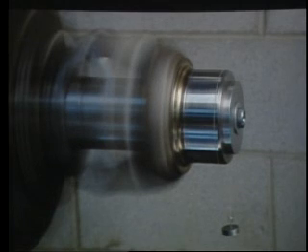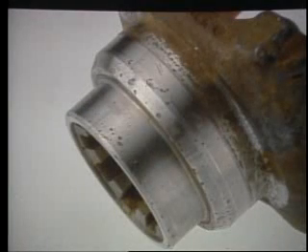Leakage would occur even though visually there does not appear to be a problem with the sealing surface of the yoke. This is an important point to remember if a chronic leakage complaint cannot be repaired after repeated seal replacement.